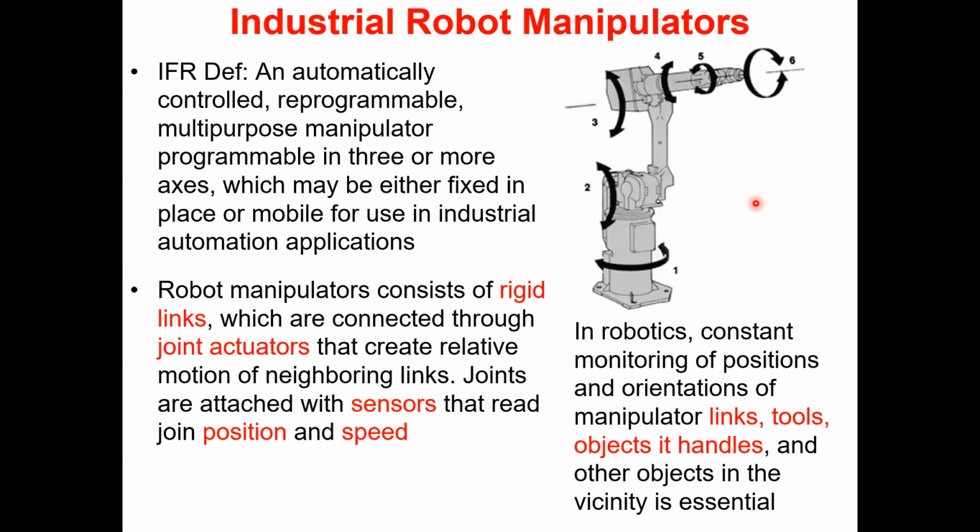In the laser cutting, in the welding, you saw how the manipulator is brought into that position and orientation. So getting to a position is one thing, but getting to that orientation together with the position is quite another, right? So you have to do this simultaneously. How do you do that? We can talk about that maybe later. We call it path planning, trajectory planning, how you bring the manipulator to the desired position and orientation before it can do whatever it intends to, welding or part handling or whatever.